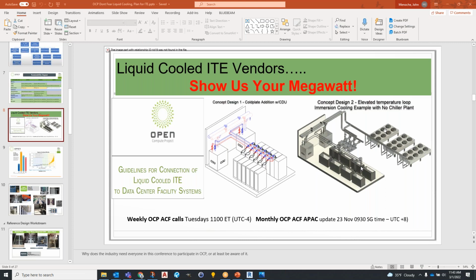So John and John, part of this, John Michele again. I use a lot of busway in my designs and 1200 amp bus. They're pretty stout fixtures, and then the bus taps themselves are in the 40-50 pound range each, depending on how long the cords are, using bigger taps and double taps. Anyway, the design may need to include things outside the manufacturer's supplies, right?